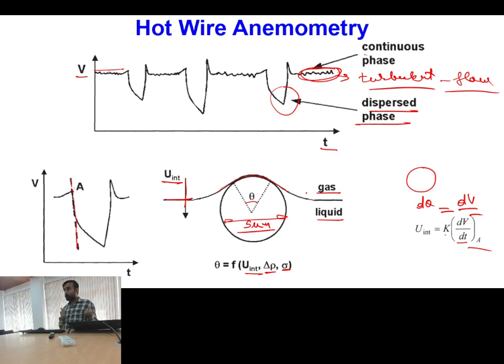But if you want to utilize this method for phase change situations where the two phases are constituted of molecules of the same component, then because of these wetting conditions, you will find that the accuracy of the system is not that good. Yes, because there you do not have a multi-component system. Typically, hot wire anemometry is a very popular method for measurement of fluctuations in velocity for turbulent flows. So we will discuss particle image velocimetry in the next class.